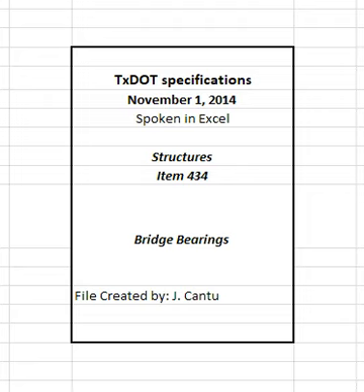2.3.3.2 Upper component. 2.3.3.2.1 Steel top plates. Provide steel top plates in accordance with the TxDOT LRFD bridge design specifications and TxDOT LRFD bridge construction specifications. Provide an ANSI number 500 or better finish on the surface interfacing with the stainless steel sheet for expansion bearings.